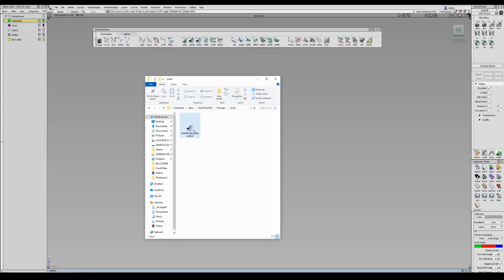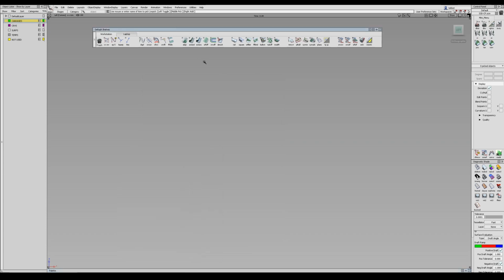So you can see here's the icon, TIFF, and I can open that in Photoshop, Sketchbook or Microsoft Paint, and create a custom icon. In this case, I just added a white line and changed the color, and then hit save, and then Alias will use that custom icon. I've seen people change these out for skulls or using other applications' icons such as Rhino or Maya.